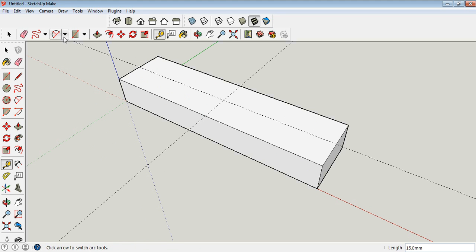Right, then use the circle. This time round it is 3 mm radius, and then we push it down all the way, or rather it's not 3 mm, it's 3.5. Right, to undo it, we press Control Z. Do it again. This one is 3.5, so that is slightly bigger than the screw that we are going to screw in. Then we shift down.